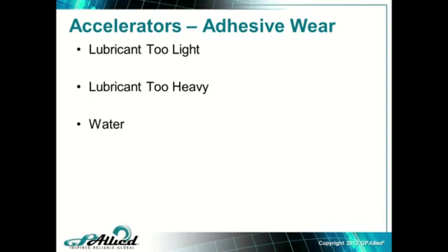And of course, water at room temperature is not compressible. But inside a lubricant wedge at 250,000 plus psi, that water is certainly not room temperature. It's water vapor, and water vapor is very easily compressed. So this is what's known as the saturation point of lubricant. It's the percentage of water in the lubricant where EHD, or elastohydrodynamic lubrication, is not possible. Basically, how much water can the lubricant hold before the lubricant wedge cannot form. Right? So that's adhesive wear.